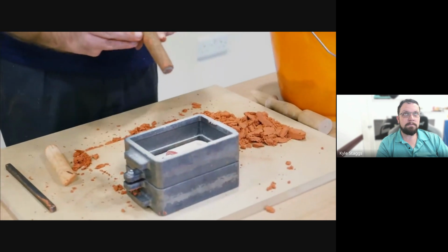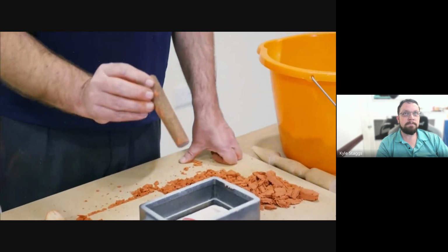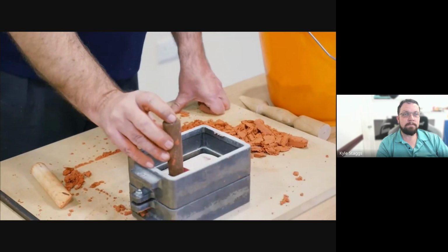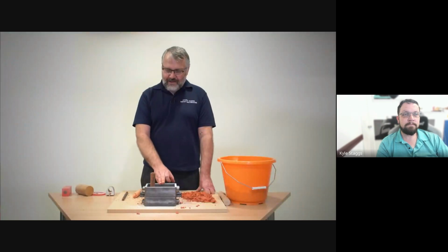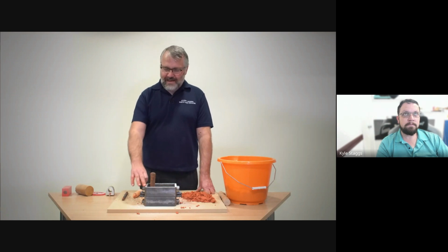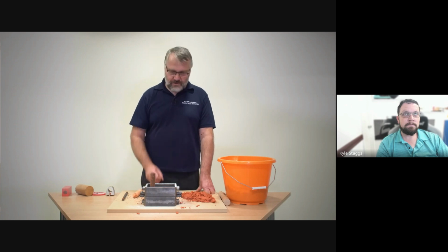I use this tapered wooden pin, known as a sprue pin, and I place it in the corner of the box. If it touches the pattern, it will damage the outcome. If it touches the flask, the heat from the molten metal will sink out and it will start to solidify before it has completed the task.